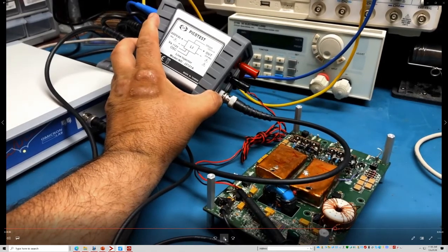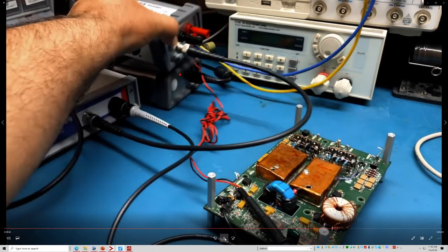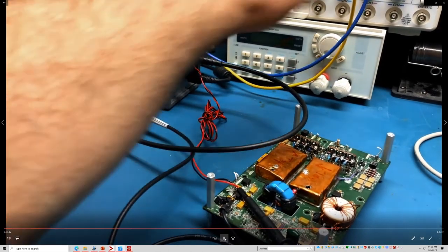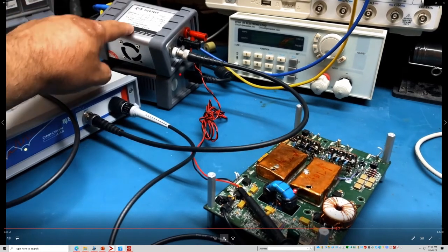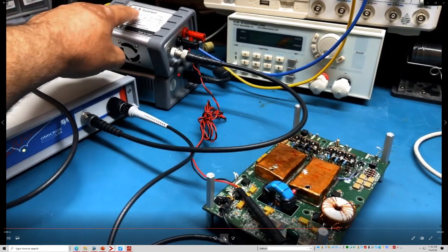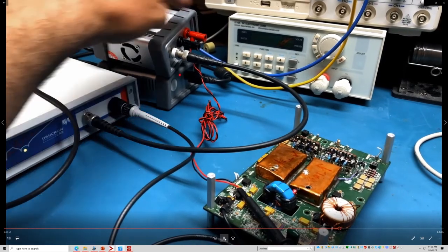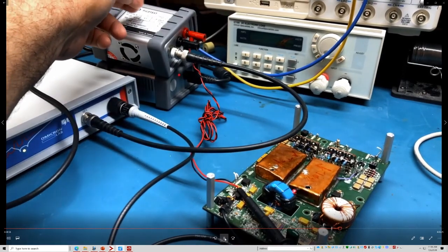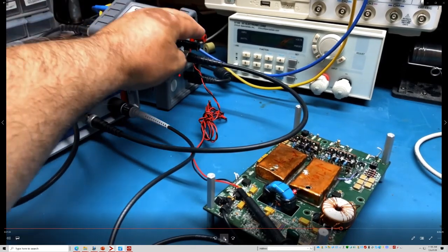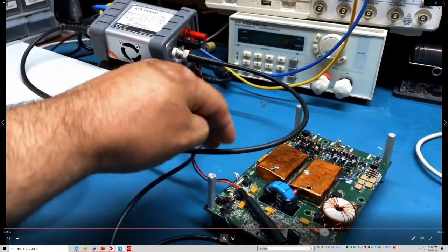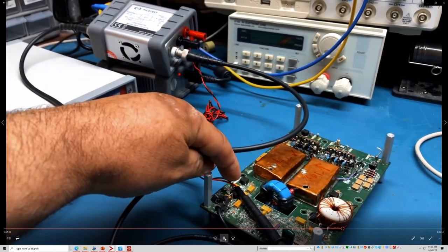This is the J2121A line injector. 12 volts is fed into the injector, and a signal is injected into the line, the 12 volts that is routed through the injector. That 12 volts is modulated with a signal, and that signal travels to the input connector of the power supply.